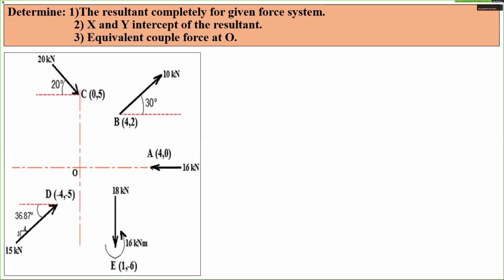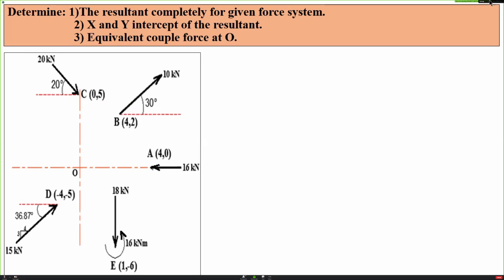Then theta, the angle made by or the direction of the resultant, you find by tan theta equal to summation Fy by summation Fx. But for the concurrent force system, all the forces pass through the same point, so the resultant also passes through the same point. So there is no need to find the point of application of the resultant. But in a non-concurrent force system, I need to find the resultant magnitude, the direction, as well as the point of application.